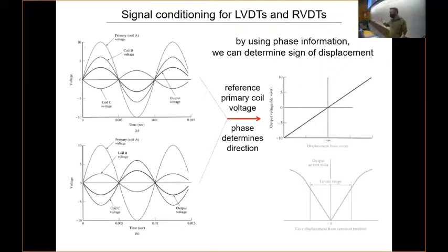And you're looking at the difference between the two of those. Even if you're in phase, where you split the signal and ran that directly into the oscilloscope, that's a shorter path than the path that goes through the LVDT. There's a resistor there. So that path is a little bit longer, and you're going to see a little bit of a phase shift even between the one that's in phase and your input.